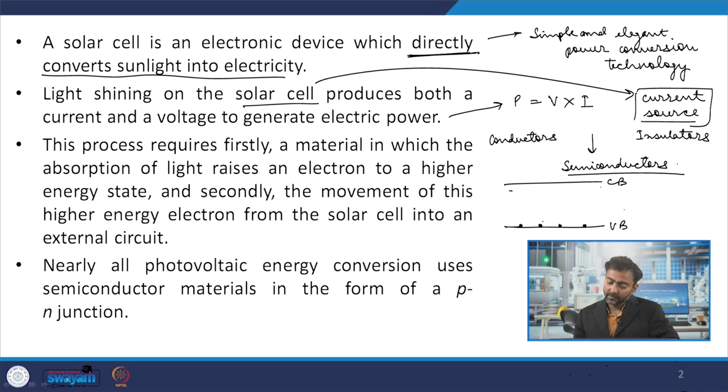However, the interesting thing is that when a photon of light hits one of these electrons, this photon of light, which is carrying some energy, let us say we call it h nu, transfers this energy, and if the energy is sufficient to cover this energy gap Eg, we call this energy gap the band gap, that is the standard term used for this.